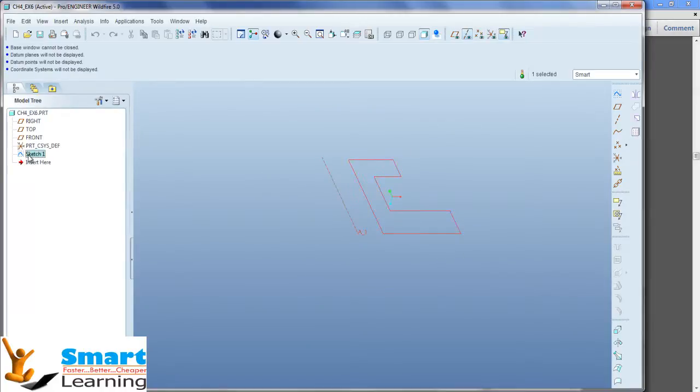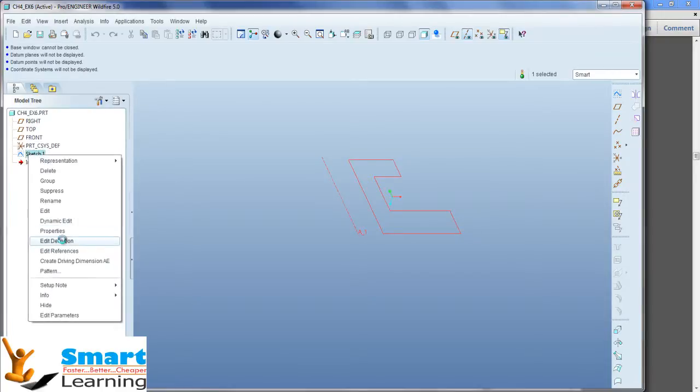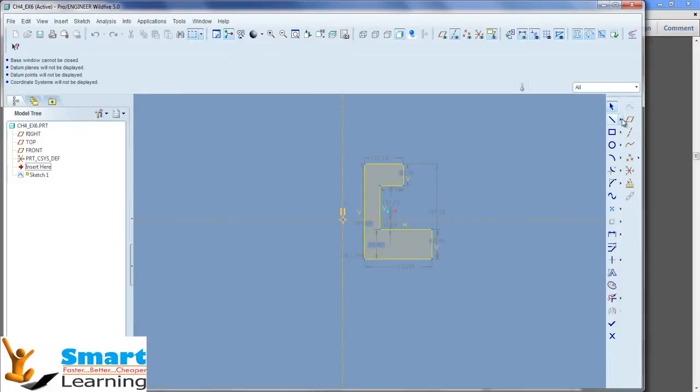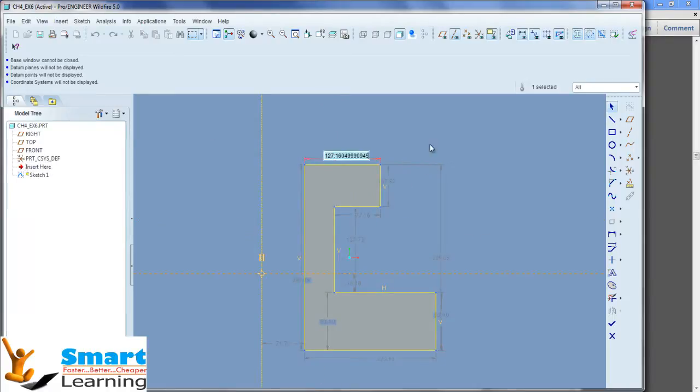So this is the external sketch which you have defined. But one thing I will show you, that for revolve I have considered this as the geometry center line, not this center line. So geometry center line converts this to a physical axis, and here we have the closed section. Let us define the dimensions.